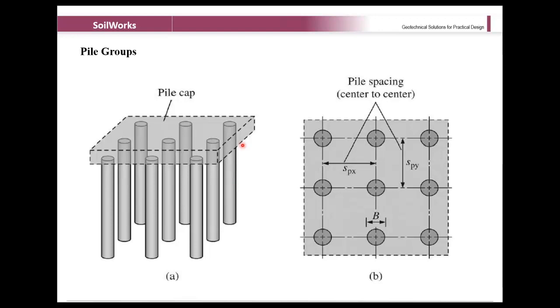So how that overestimates your foundation design, and how the approach I'm going to deal with, a nonlinear spring, can provide the correct approach, will be dealt with now. Hence, that's why we need to go for nonlinear springs, PY nonlinear springs, using PY nonlinear analysis. That will be dealt with in this webinar now.